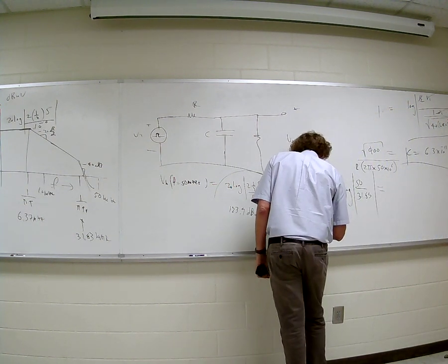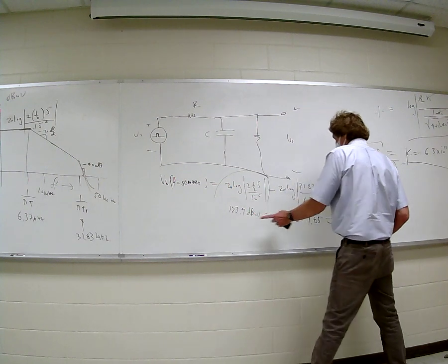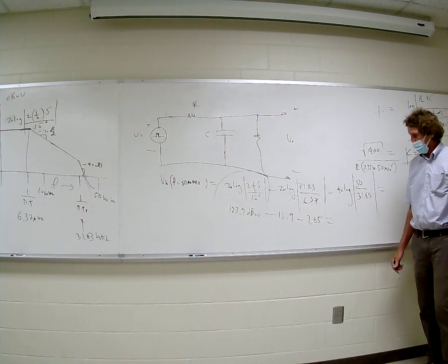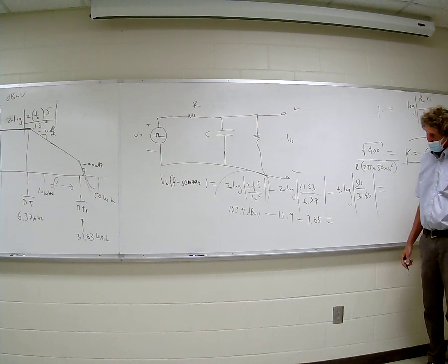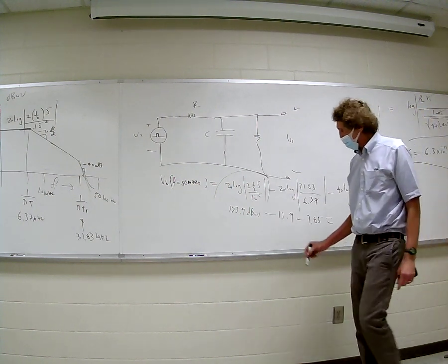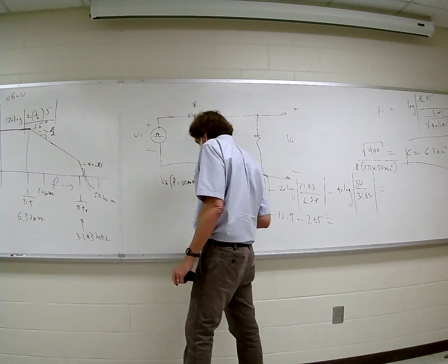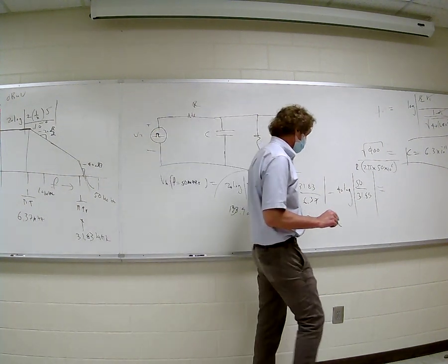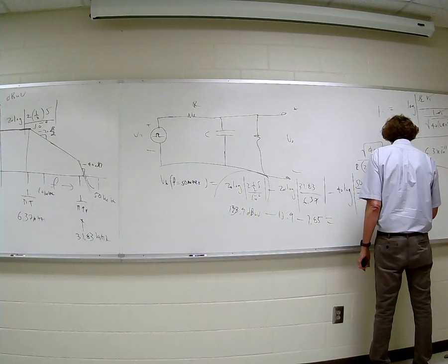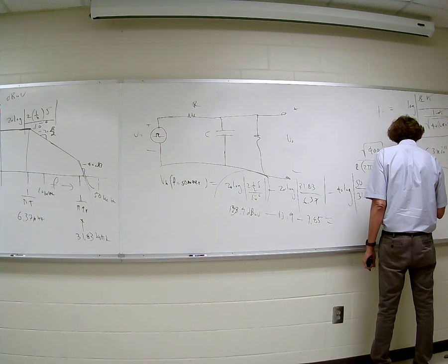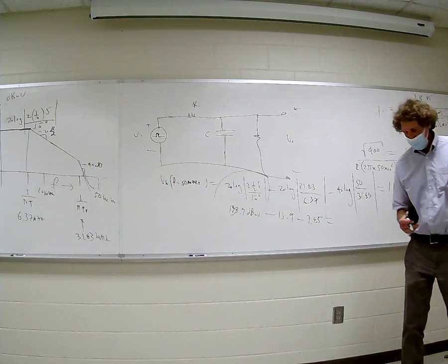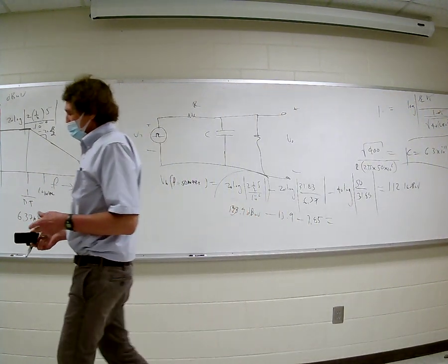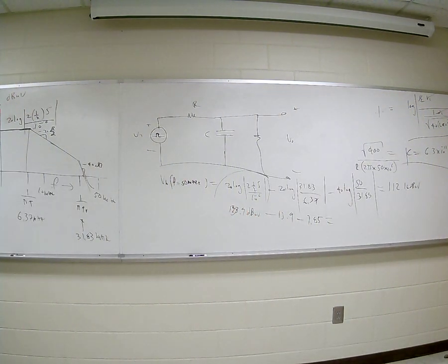All right. And this is dB microvolts. Now do the math on this whole thing. Subtract 13.9 and 7.85 from 133.9. That comes out to 112.16. So that's the signal strength in dB microvolts at that signal that we're putting in at the fifth harmonic going in.